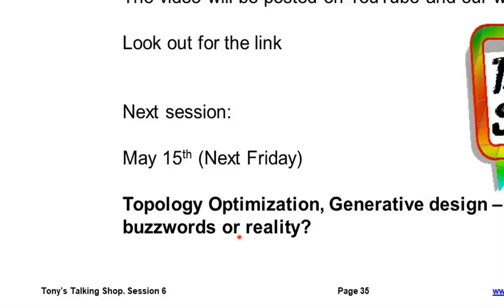To do the Neuber intercept between the Neuber notch and the power law is easy from a mathematical point of view. Otherwise, there's lookup tables and other approaches. Again, if I get a chance on the curated video, then I'll try and expand a little bit further on that. Badri has the question, as per Neuber, we can do a low cycle fatigue without elastic plastic nonlinear analysis.